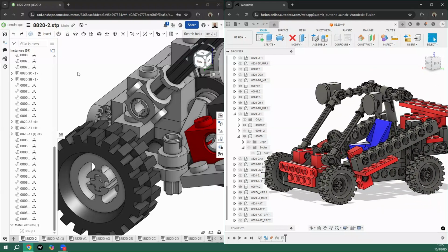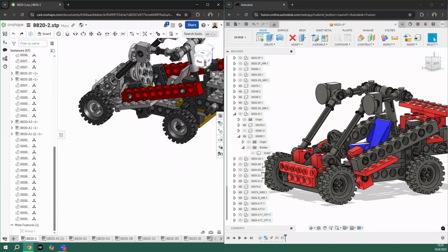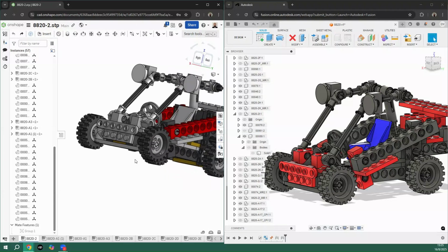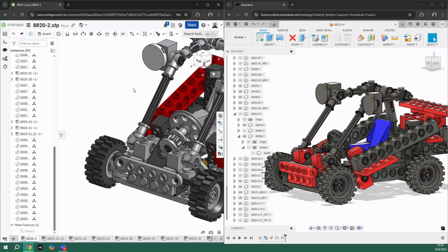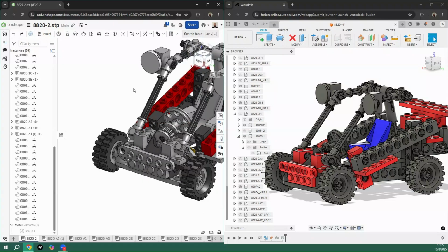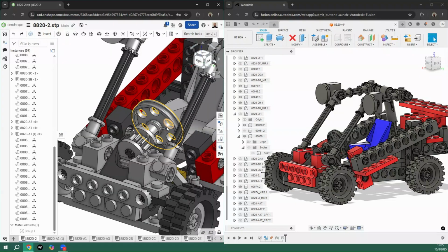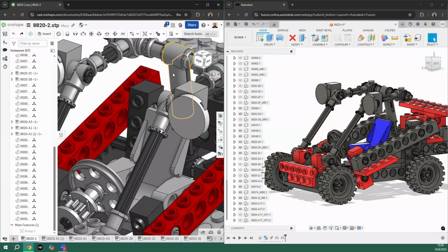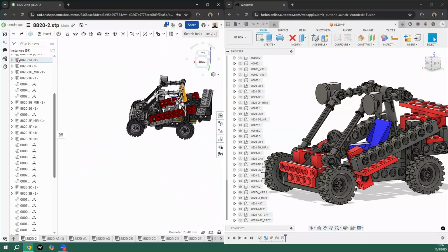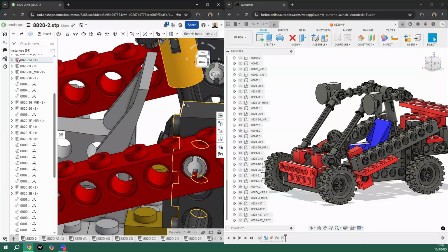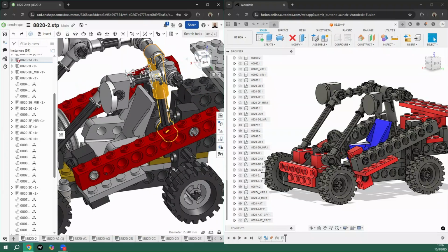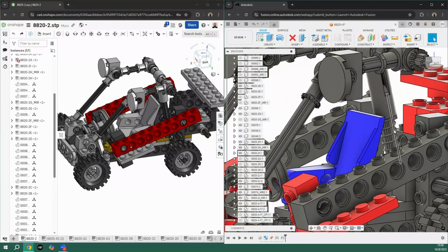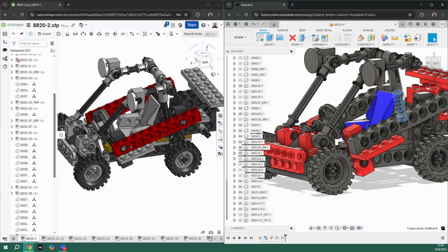Okay, so that's the similarities on how to constrain something, fully constrain something, right? So this subassembly has internal components and the components are not going to move at all. Okay, so the other practice that happens in these two pieces of software is to group everything, right? So if I want to give a potential move to this component because it is going to be spring loaded. By the way, the spring is missing in this model. Well, in Fusion you can see it. There is the model of the spring.